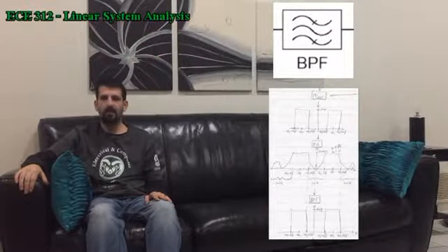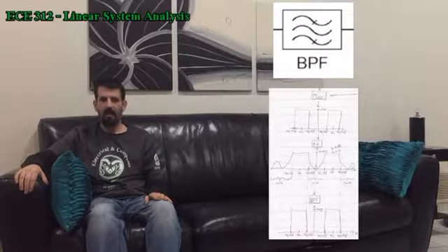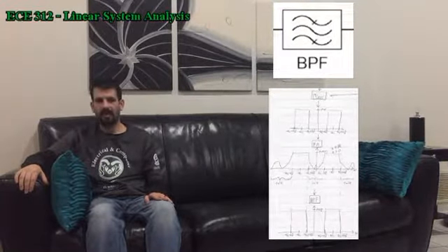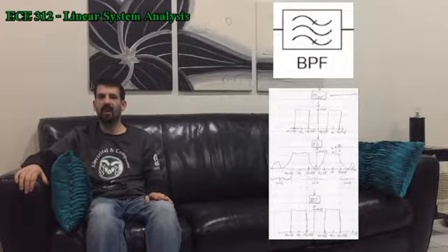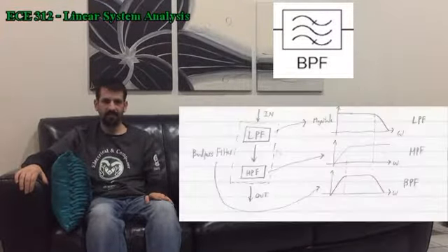From ECE 312, we know that the output signal from the power amplifier is a linear combination of the modulated signal and its harmonics. So a well-designed filter can remove all harmonics while leaving the original signal unaffected and clear.